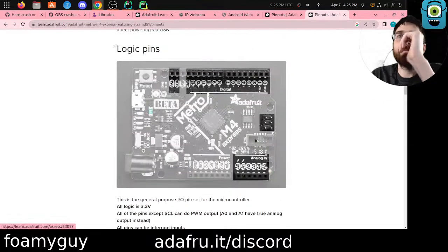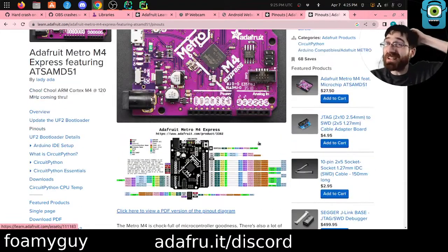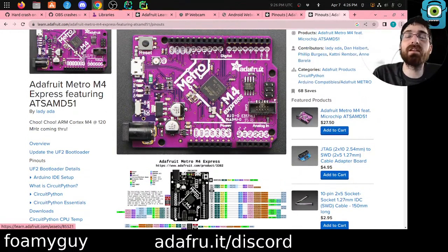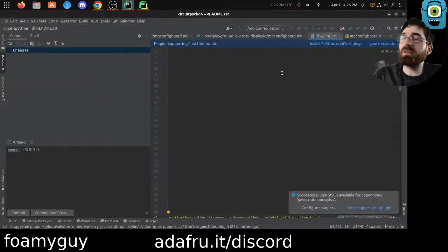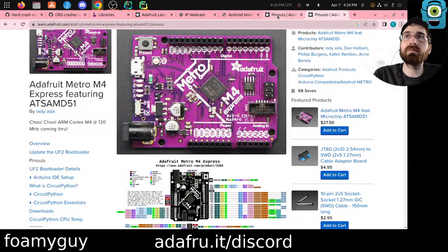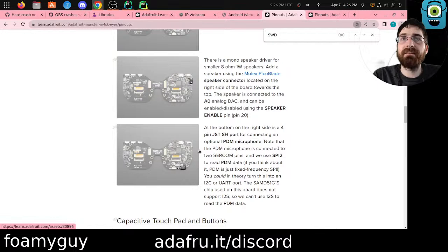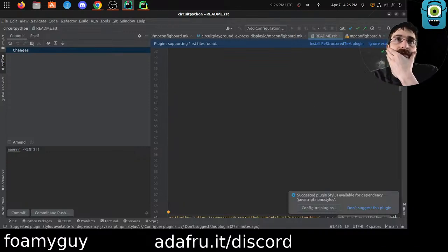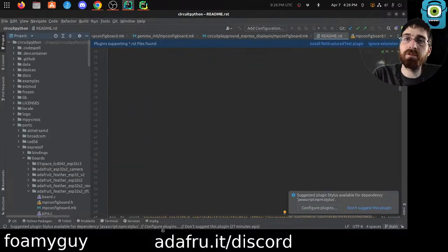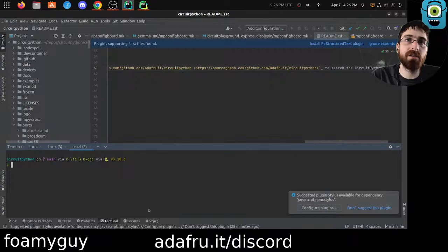I'm pretty sure that's this, but I don't think any of that stuff is broken out, so I don't know if or how we can get more full stack traces. I guess let's try a debug build first. SWD, thank you. SWD, nothing. Okay, let's just try a debug build and see if we do get anything more interesting out of that. This will be from main as well, which means it won't have my additional prints.